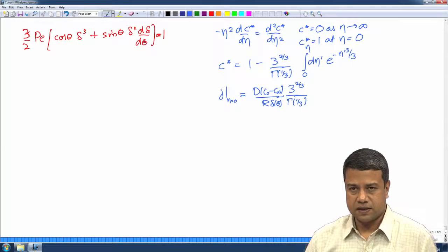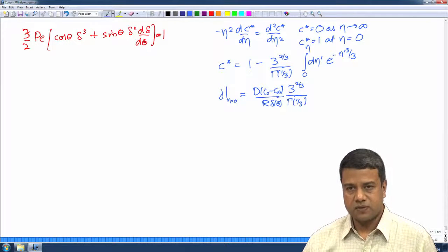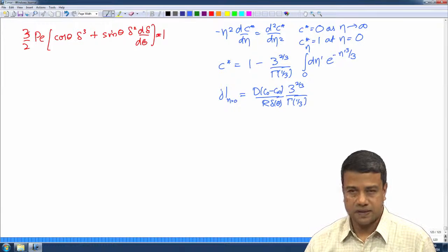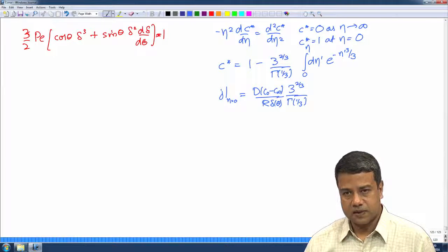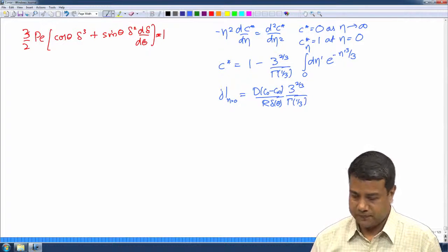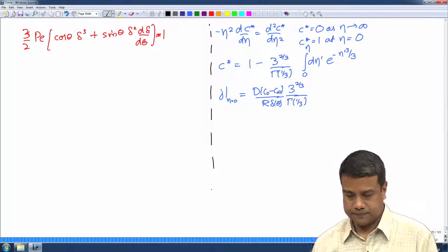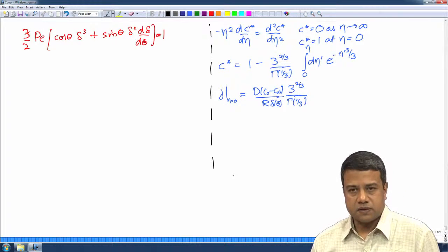because the boundary layer thickness and all length scales in this problem have been non dimensionalized by r. So, the actual physical boundary layer thickness is r times delta. So, that I have to substitute for the delta in the previous case. So, this solution is the same. Now, I have to solve this first case. How do you solve this?